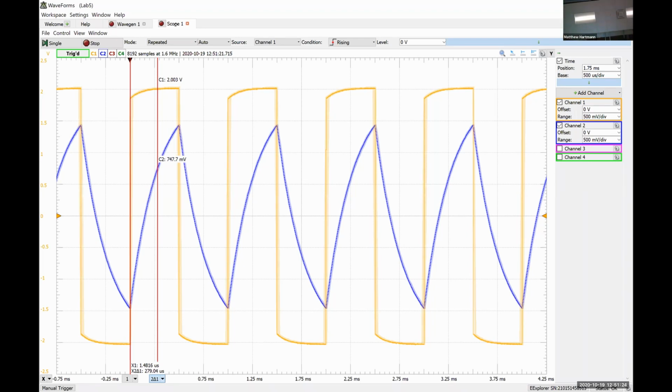So could we use these higher frequencies to get a good estimation of what our time constant is? So that's a yes or no question. No, right? Because if we never allow it to settle, then we don't have a good estimation of what's going on at y at 0 minus and 0 plus, and we certainly don't have a good estimation as to what's going on at y at infinity.